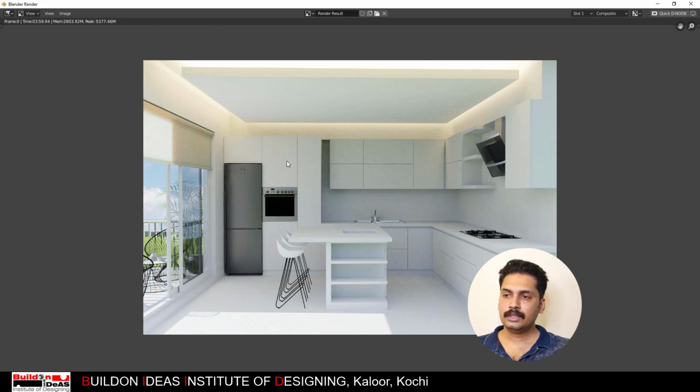Okay, now it looks nice, but the only thing is like in these glasses the light is not passing in. So to fake that, we have to make these exclude from the shadows so that the light passes inside. And also there is some light burns out here. The light above this is slightly high, and we'll have some ceiling lights and the hanging lights and stuff like that. We'll have one faucet out here for this wash basin, and then some props inside. So props I'll not be modeling, I'll be just placing it from my previous works, and then give the rest of the materials and finish it off.